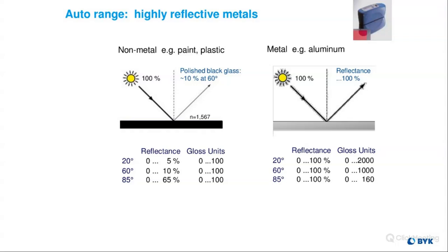And so that light's going to absorb into the material differently. The best recommendation I would have in such cases, if you're doing comparative measurements on objects with a lot of film build, is to really measure and compare similar samples to one another.